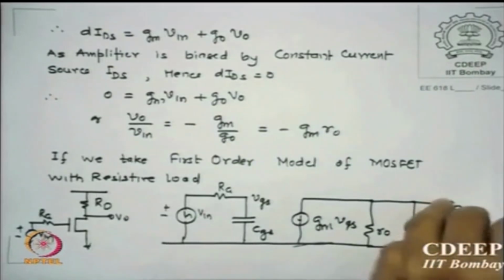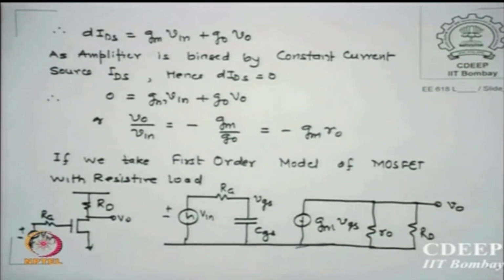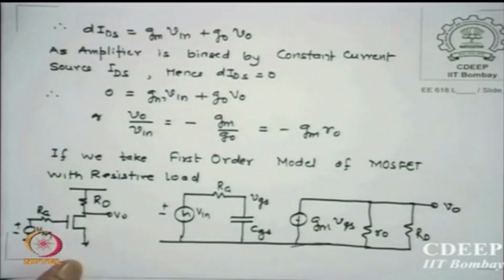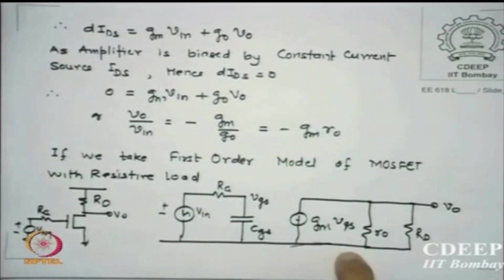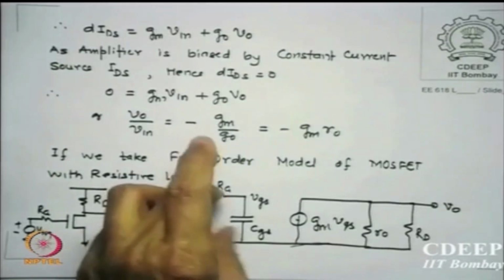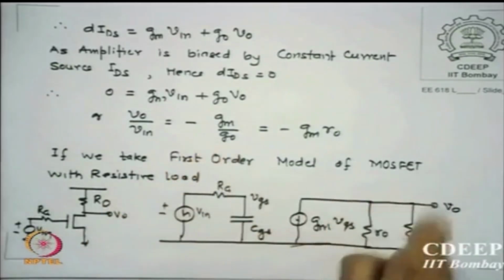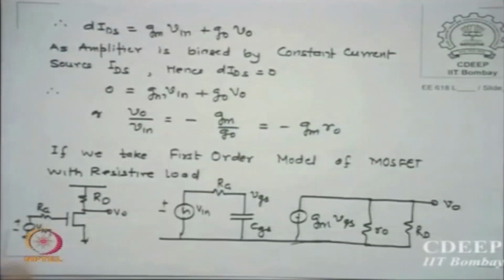So this is my equivalent circuit. Why am I doing it? I want to give some numbers which are very interesting in designs, and that is why I am looking for them. Is it okay? This is the equivalent circuit, there is nothing great, I just put two terms here and an additional term RD here. This is still low frequency, so CGD is open circuit, 1 upon omega CGD is still infinite enough to neglect, so open it.